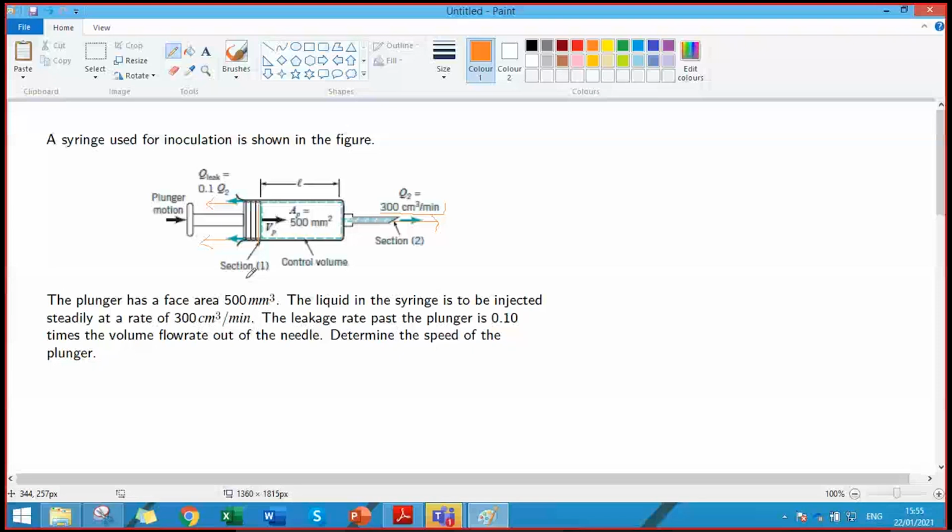No, sir. It's moving. So it moves with the plunger motion. Yes, as the plunger moves, the control volume also decreases in volume, right? That means the control volume is moving. Plus, this control volume is also deforming, because the face attached to the plunger, the control surface that we drew on top of the plunger, will also move and deform, right? Yes, sir. So it means it's a deforming control volume.